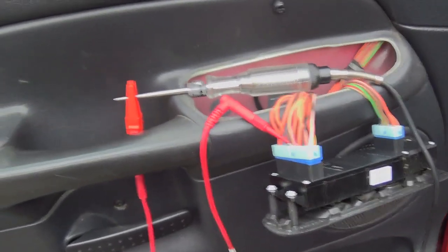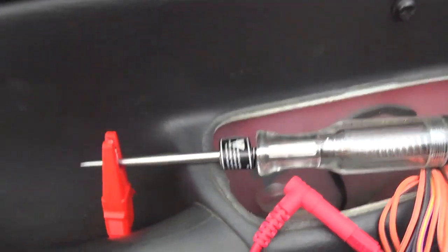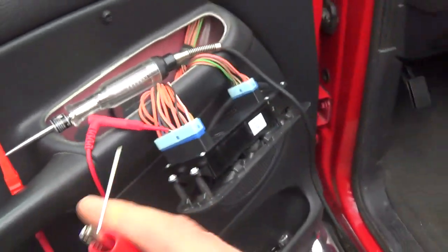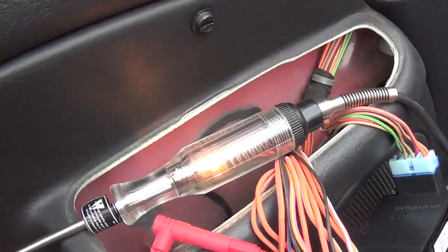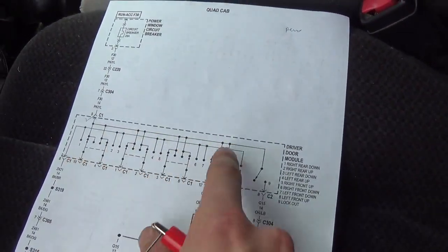Alright guys, for the sake of reliable testing, we actually have a proper connection to our positive, and that is hooked to the end of my test light. Okay? Now if we touch this side, this jumper, to something metal, test light should light up. Okay, now we can do our ground checks here. So my theory is all of these pins here are constantly grounded, not constantly powered like the diagram tells us.